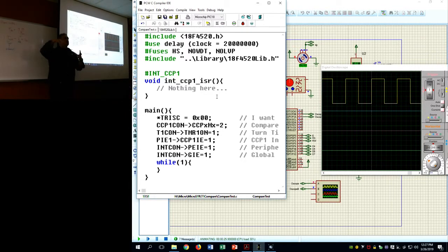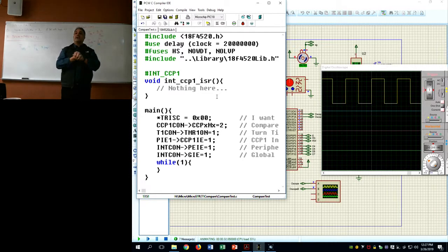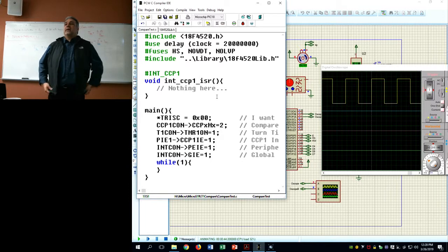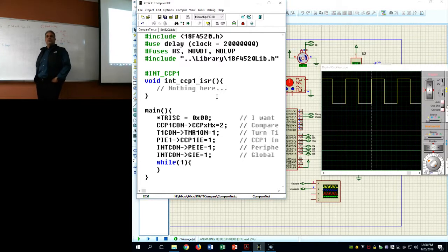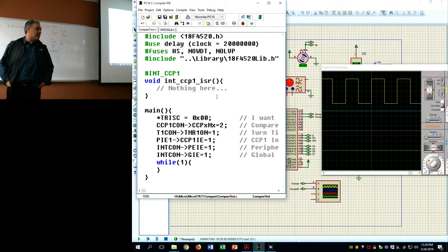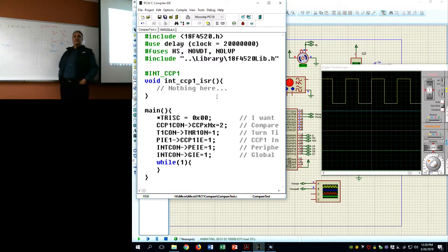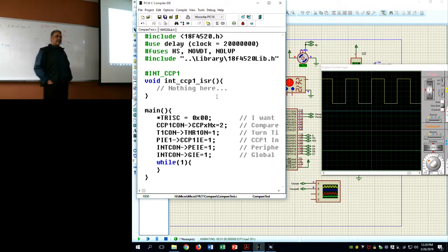Always remember that as you mature in your microprocessor careers, make sure that you get to know your circuit and allow the circuit to do what it was designed to do. Don't do in software what a piece of hardware could do. You will never be faster, right? That was the magic a professor of mine told me a long time ago, and I've been stealing that line forever. A very good firmware programmer is the one that writes the least amount of code. Just let the hardware do what it was designed to do. Getting to know your hardware is extremely important. This is why when you look at software engineers programming firmware, they write really funny code. It's like, what are you doing? You don't understand your hardware, do you?